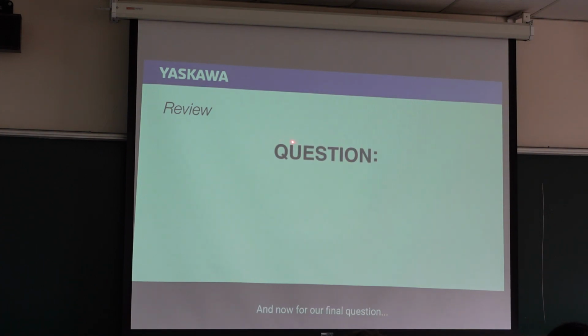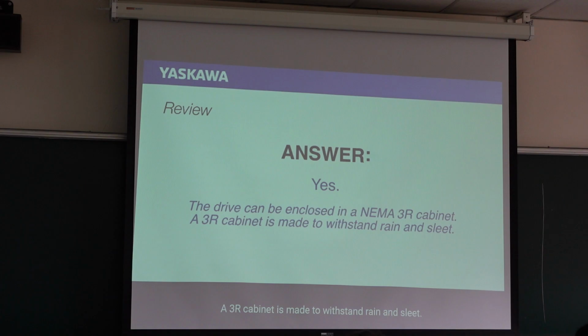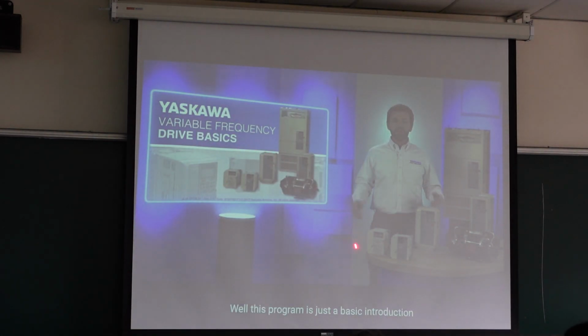And now for our final question. Can a drive be mounted outdoors? Well, of course it can be. Yes, enclosed in a NEMA 3R cabinet. A 3R cabinet is made to withstand rain and sleet, rain and snow.